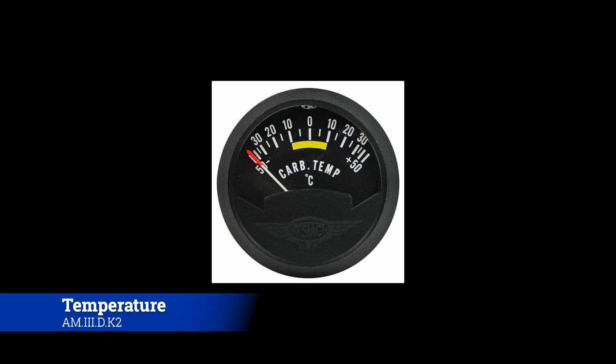And it's also fairly easy to detect if you just simply know what you're looking for. Carb ice is pretty telling. You're going to be in a cold, damp environment, and the engine's going to start running rough, almost like it doesn't have enough fuel, and it's going to kind of come out of nowhere. But if you have a carb temperature or air temperature gauge on there, it will help take a lot of the guesswork out. You can just look at it and you know that, oh, look, it's super cold, engine's running rough, it's probably carb ice. Let's put some carb heat on there and see if we can get that ice to melt.